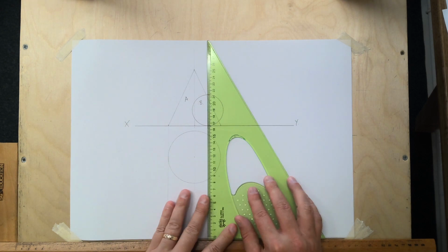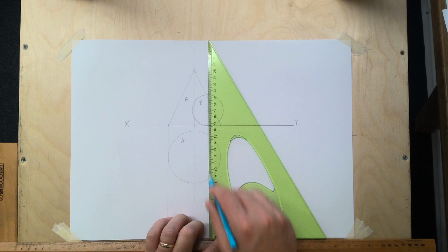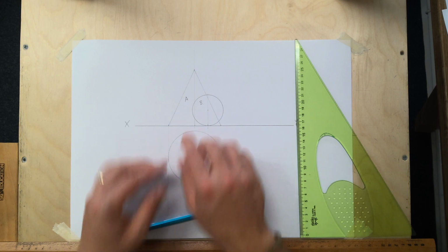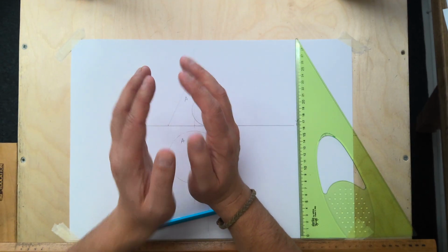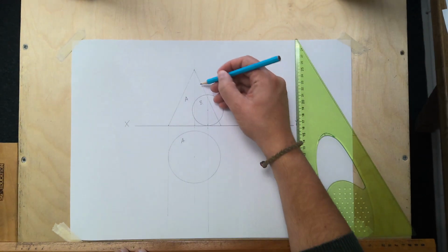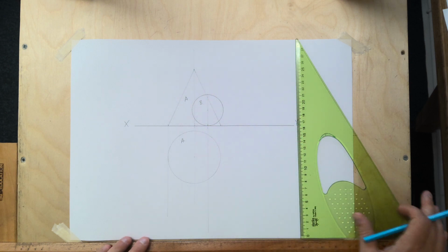So we're going to drop down our center. So this is A. I'll just put that back up there. Drop down our center point. Now we don't exactly know where it lands. So therefore, we need to rotate our object. We need to get our cone and our circle, and we're going to turn them till we're looking straight in at them, so we can get an edge view of the sphere making contact with our cone.